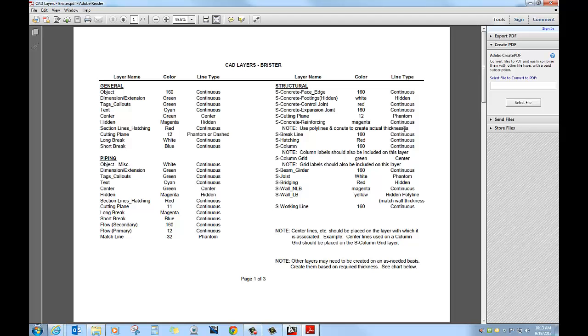And with a donut, again, you can set the center diameter to 0, and on that donut set the outside diameter to whatever diameter you need for that particular rebar. For instance, number 4 bar. Hopefully you remember from materials that a number 4 bar is 4/8 of an inch in diameter, so it's a 1/2 inch in diameter.